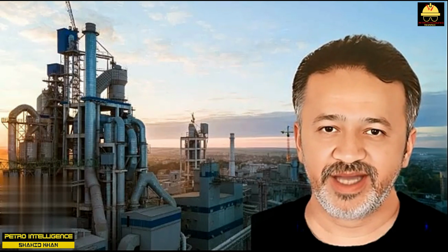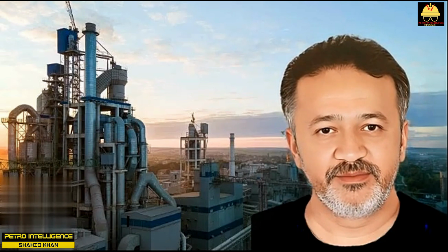One-pass tube side exchangers. I have not been completely accurate in the preceding discussion. Many exchangers are designed to bring the tube side fluid in one end of the shell and out the other side. This is a true countercurrent arrangement. To provide for thermal expansion in such exchangers, an expansion joint is provided. These expansion joints are prone to leaking. They represent inferior mechanical engineering practice.